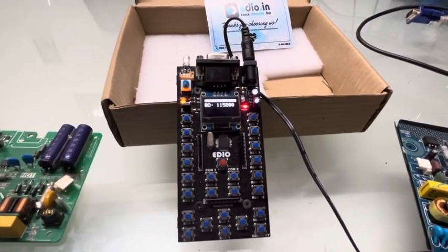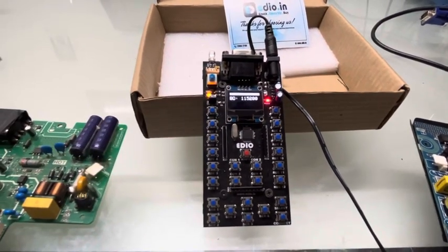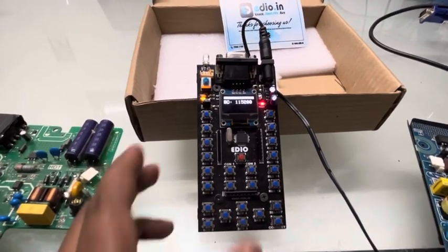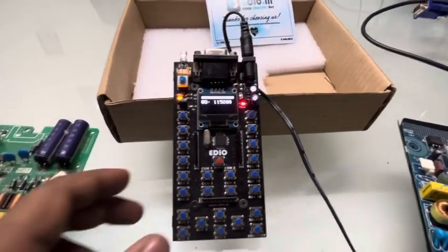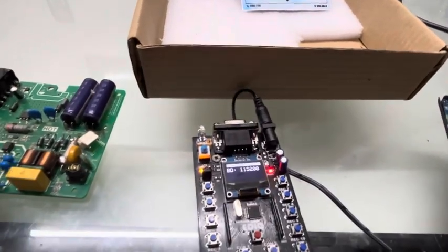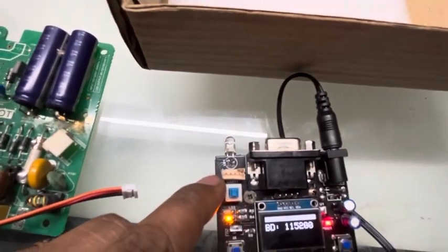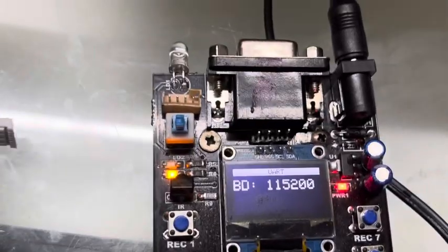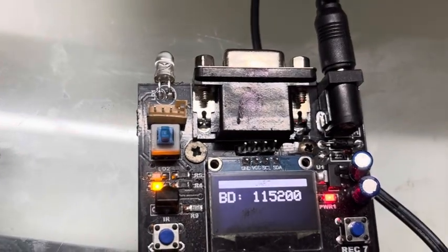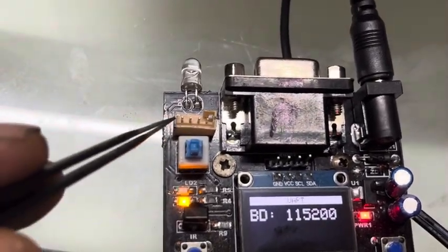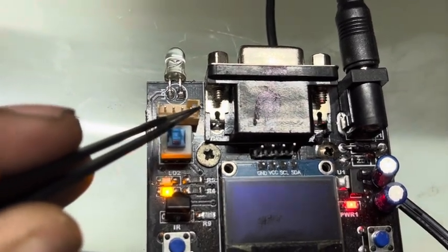What you are going to do is first connect your UART port using any type of cable. In some motherboards they don't have any ports, they are using test points. In that case, we provide one connector here. In this connector, the first pin is ground, then RX, TX, and 3.3 volts. We provide this type of cables. In these cables, one end you have to connect here. You can connect directly.